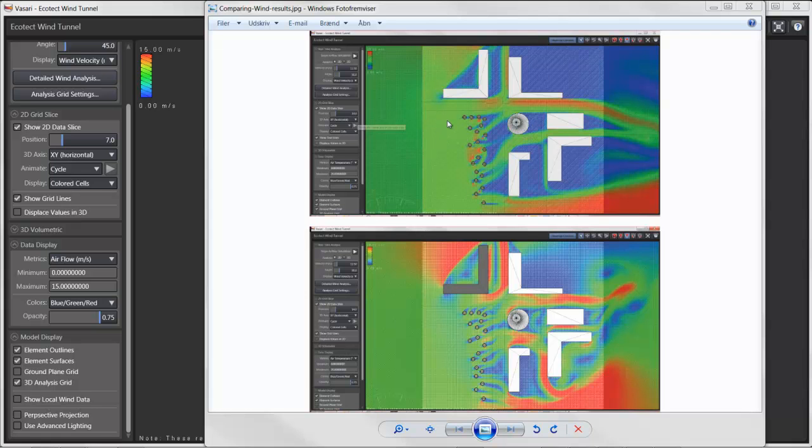Here is the first one. I used 8 in the voxel size and 4. And as we can see here, it's of course getting more detailed, more accurate by having smaller voxel size. But it takes a longer time, and sometimes you don't have time enough for waiting on the results. But maybe on the final simulation you want to send to your client or in the scheme, you could use a smaller voxel size to get a more accurate and more fine result. But for early stage, higher voxel size is okay, because it's only an assumption of how the wind could be on this site.